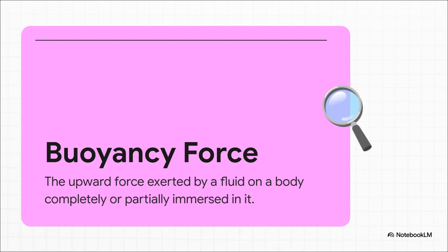It's the buoyancy force. It's the exact same force that makes a boat float or a helium balloon shoot up into the sky. In our case, the object being pushed up is that pocket of warm, less dense air, and the fluid it's floating in is all the cooler, denser air around it. This buoyancy, this is the real engine driving the entire process of natural convection.